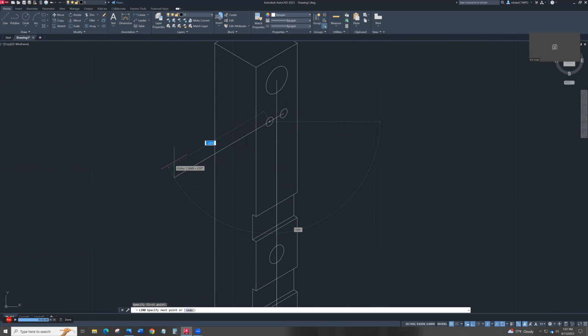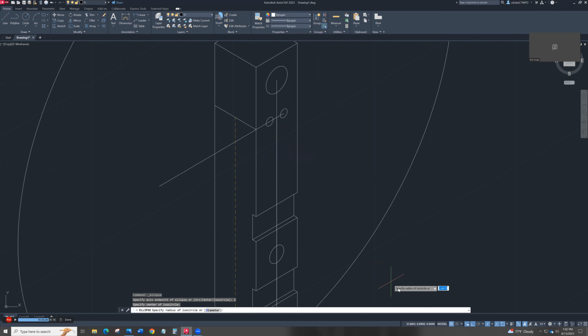draw a line from the center, just go across here. All right, then I'm going to copy this line. I'm going to copy here from this endpoint to this intersection. And then right in the center there, I'm going to have that tap ball. Now notice if I go to isocircle and I pick the midpoint where it's going to be, it's going the wrong way.